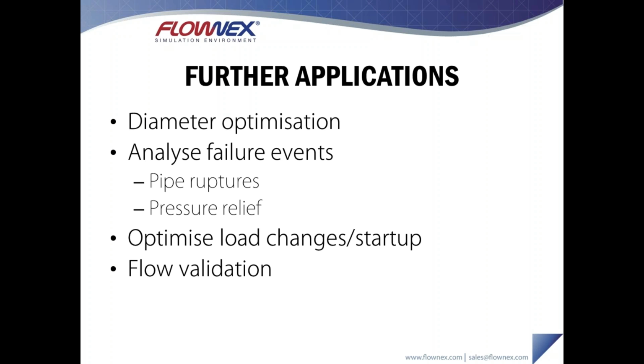We can also look at optimizing load changes. So Flownex itself has an inbuilt control module. There's another webinar on that. I'd strongly recommend you take a look at that. It's available on our website. And using these control components, we can link the control simulation to the fluid flow simulation and start looking at the rates at which we change particular components, say valve openings, for example, or pump speeds, and look at optimizing these to ensure minimal stresses on our system as well as fast load changes to match the demand.